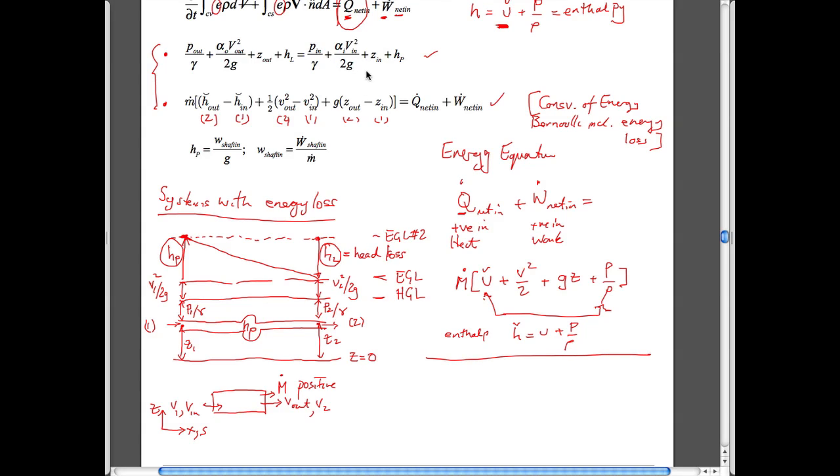It's written kind of backwards here because this is the upstream part and this is the downstream part. But if you write the Bernoulli equation as you've been used to having it, it's pressure head upstream, plus elevation upstream, plus velocity head upstream, plus the pump. So in other words, if you look at this diagram here, that's kind of exactly what this is. These are units of length, so this is a pump head, so to speak, units of length also. And so this is the right-hand side of this expression here.